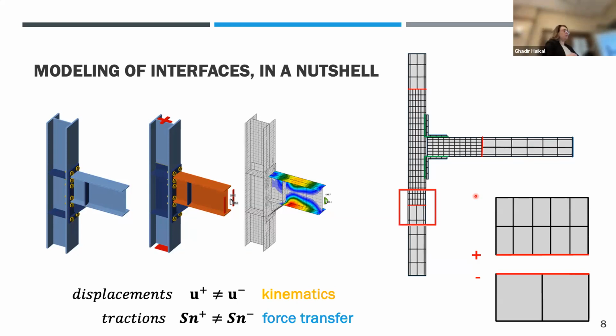Okay, so S here is the stress tensor, N is the normal to the surface, and how we calculate the stresses on that surface is through this product of S over N. With finite elements, we're approximating displacements, and we have no control over the stresses as a result of that approximation. And therefore, if the displacements are different, because they're different meshes, then the stresses will also be different. And what you'll see later is they're actually going to be much worse.